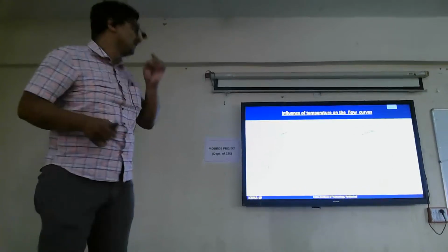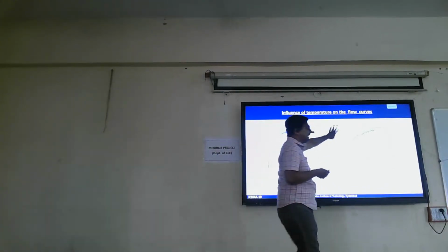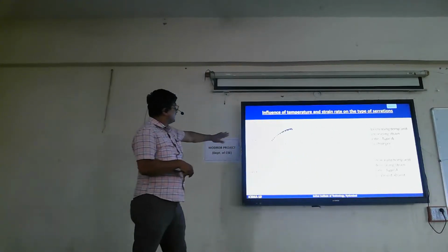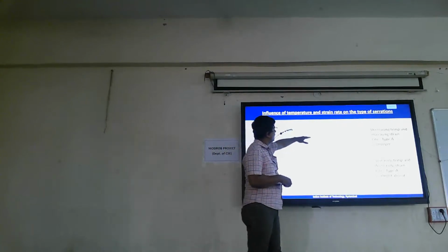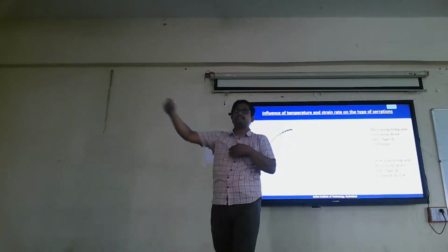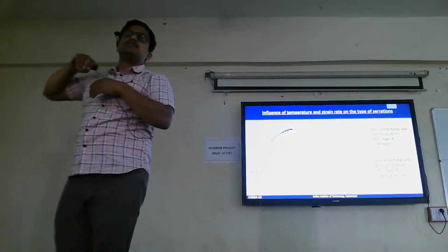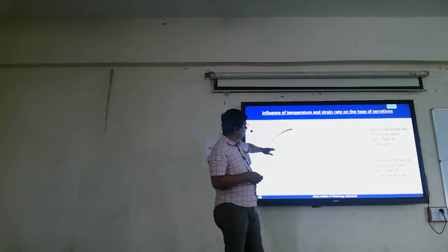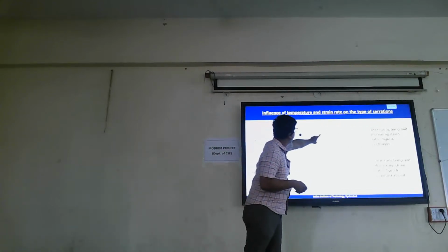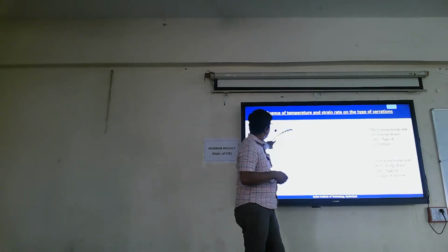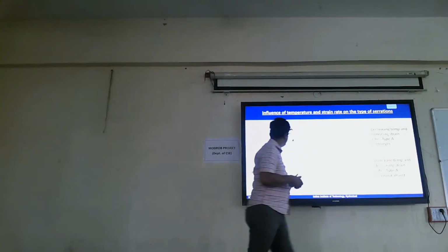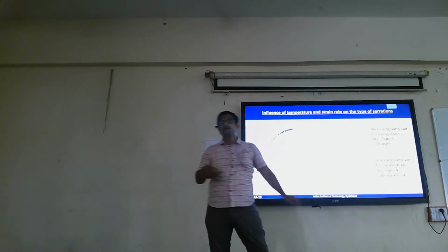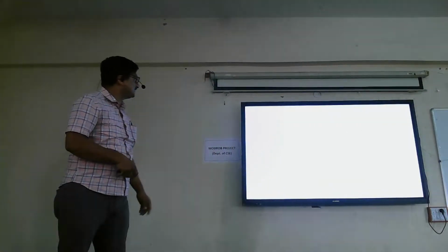So this can be dynamic strain aging, but is it really the responsible mechanism? Then start looking at the serrations. The serrations are of different categories, because they can be A, B, C, D, E types. Basically, we found that the serrations can be of A plus C type, but we are not going deeper into that. As a function of strain rate, A type serrations become dominant. As temperature increases, C type serrations become dominant. Why? We are not going deeper into that. We published that.